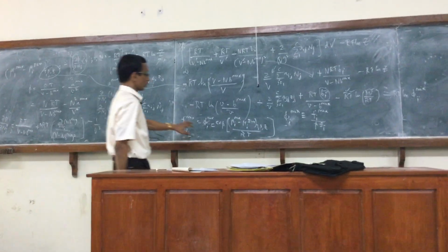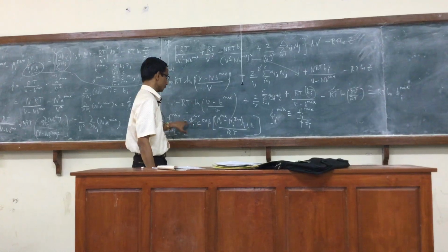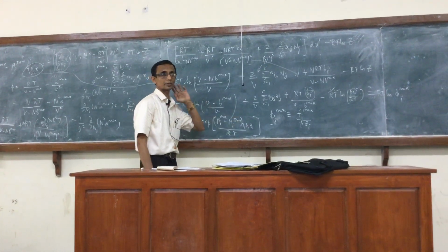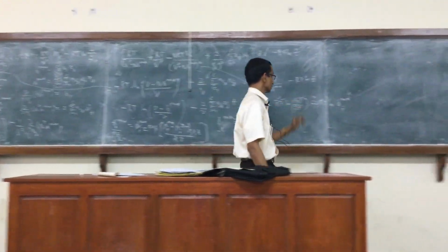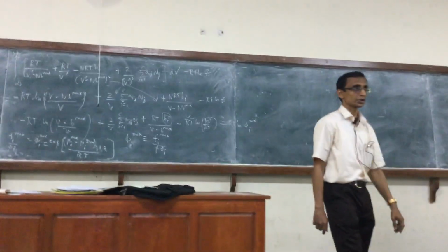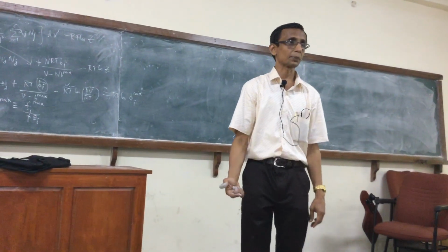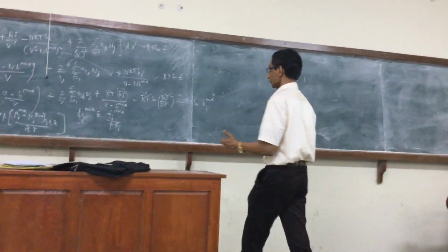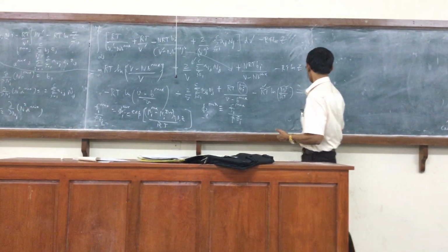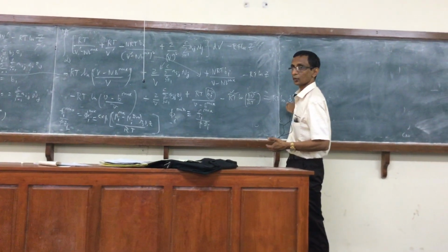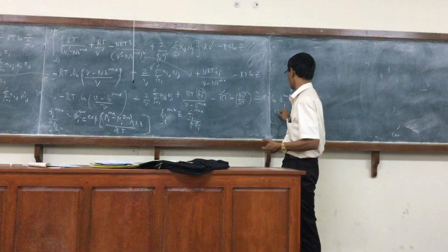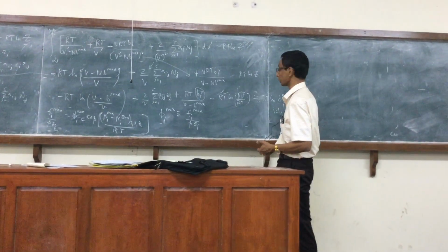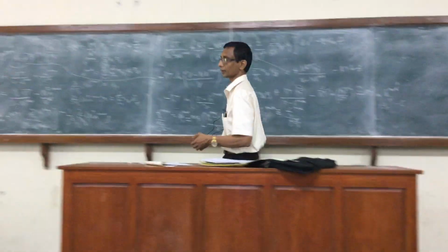So this is the fugacity of a component in the mixture. RT logarithm would give me the departure function, the departure function of the chemical potential evaluated at the same temperature, pressure and mole fraction. And for the ideal gas mixture, it is RT log of the fugacity coefficient, and there are obviously C such coefficients in a mixture.